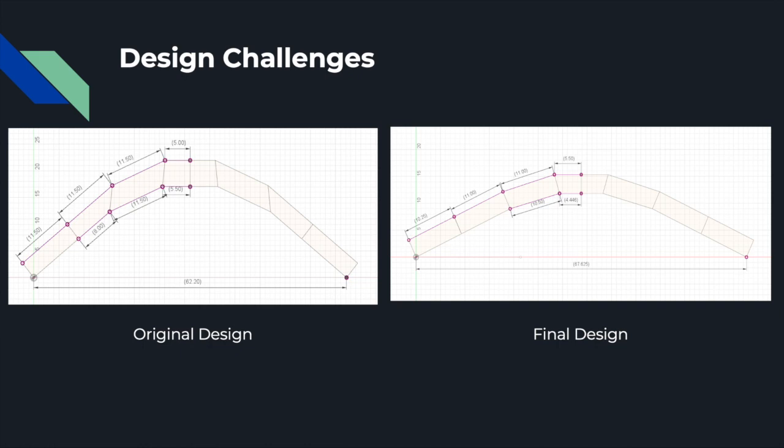Following this discovery, we tweaked our design to what it is on the right side of this slide in order to allow for the central piece, our capstone, to have better vertical support from the other sections of the bridge. Undoubtedly, while these changes cost us time and materials, it was worthwhile considering the risk of premature collapse before we hit 60 pounds. Thus, we salvaged what we could, like the central piece, which we merely flipped over and adjusted accordingly. In the end, our design was able to comply with every constraint except that one requiring the bridge to be 5 pounds or less.